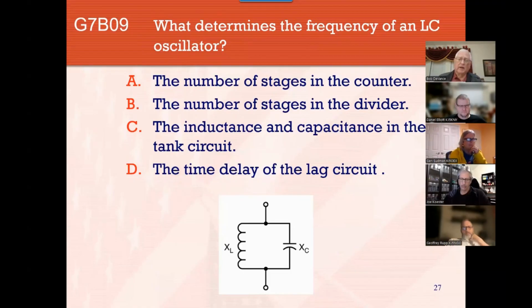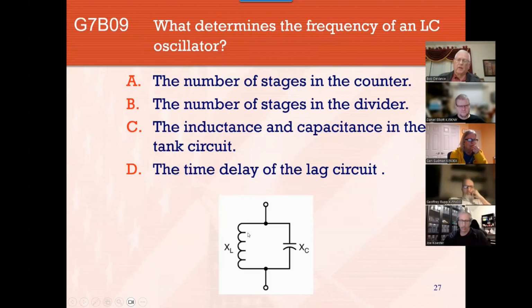The tank circuit. Now, the reason I put this little diagram down at the bottom there, that's what we call a tank circuit. The reason it's called a tank is we apply power and stick a signal into this thing. The inductor charges up slower than the capacitor does. Capacitor charges up. It just starts to discharge back through the coil. The coil charges up as the capacitor discharges.